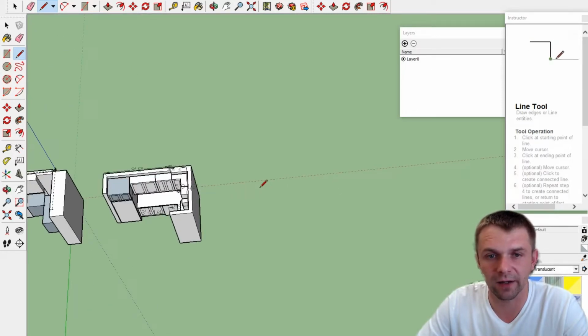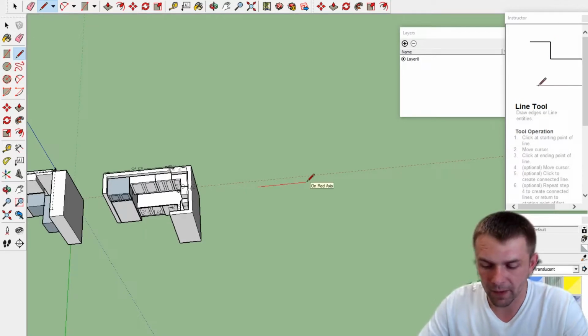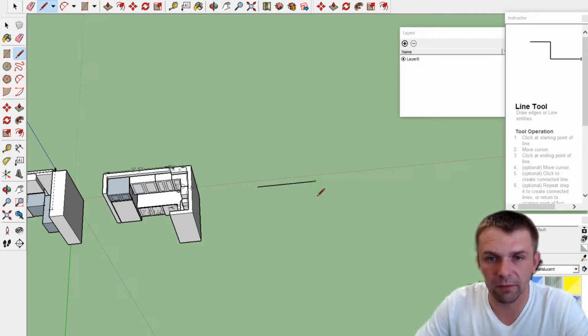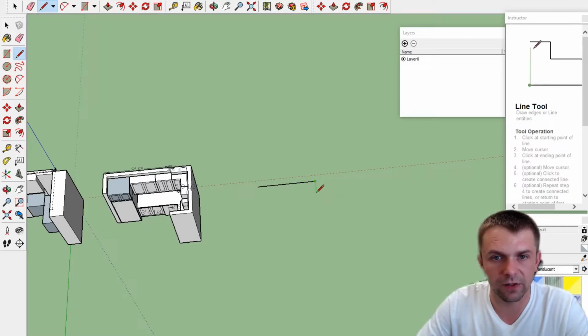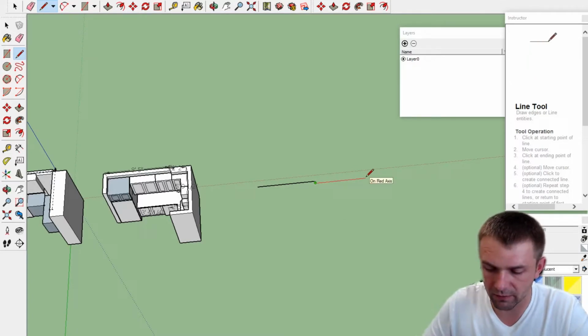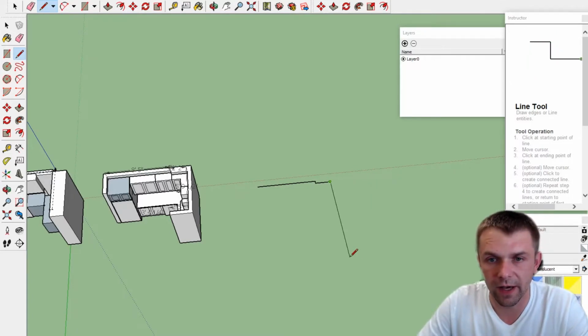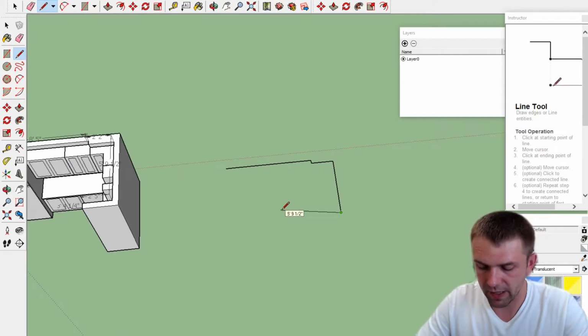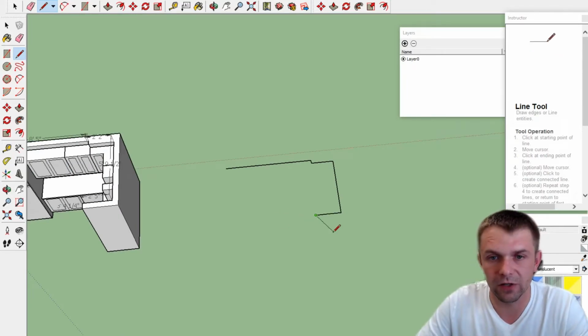It doesn't have to be on a red line. So I'm gonna start right here. I know it's 101 inches this way. Then we have a wall coming out for 4 inches, and the green line is indicating that it's going in this direction, 4 inches, and then we're going 26 inches, and it's 69, and again 69.5 this way. And the wall comes out, there's a half wall that's 29 inches, 6 and 20 and 35 inches this way.